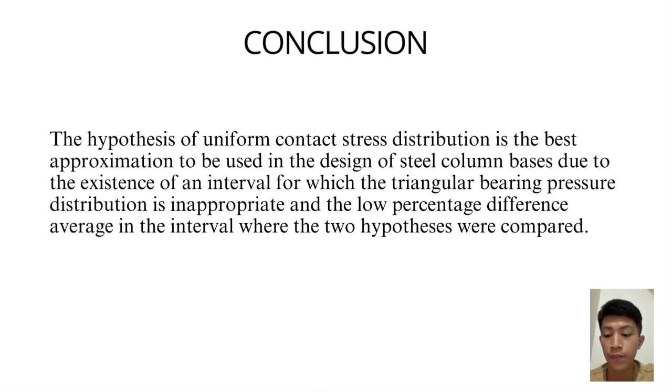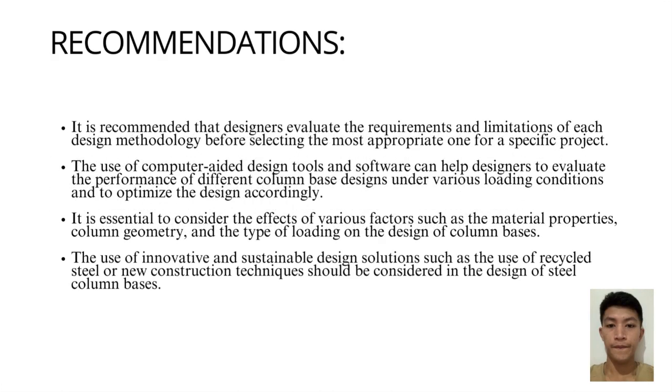Moreover, the comparison between the two hypotheses shows that the percentage difference average is low in the interval where the two hypotheses were compared. This means that the difference in the results obtained using the two hypotheses is not significant, and therefore the hypothesis of uniform contact stress distribution can be used as a reliable approximation in the design of column bases.